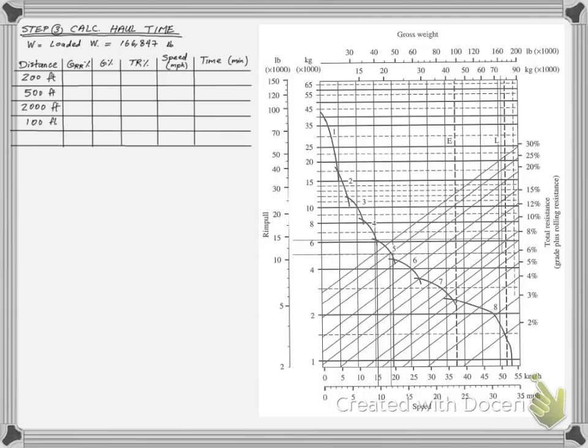We have 5 segments, including an acceleration segment and a deceleration segment of 200 feet each. Each of these initial segments has an average speed of 6 miles per hour, regardless of the rolling and grade resistance.